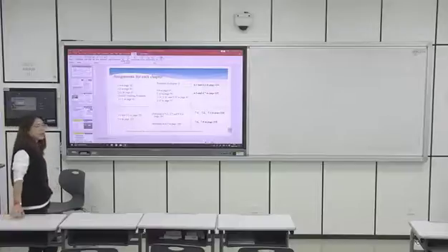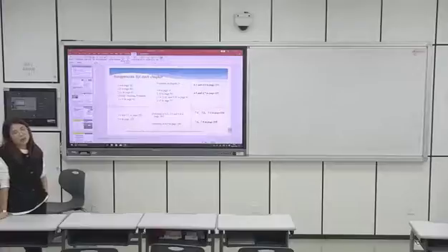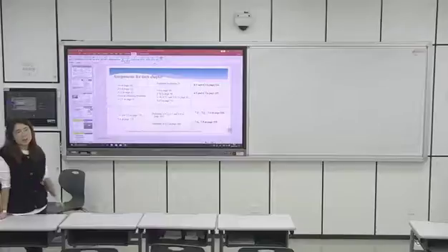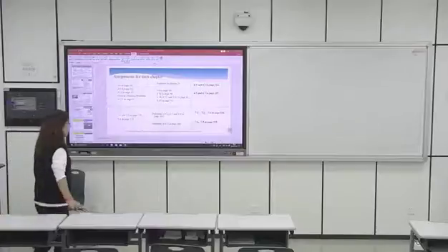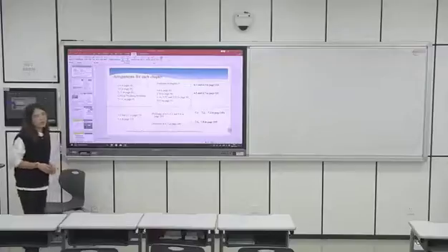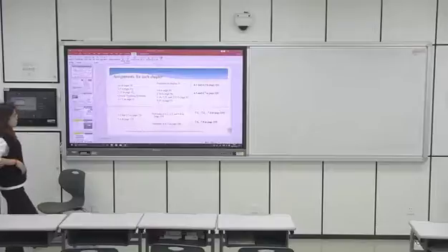And density. Density, we say that we have normal density or natural density. That is the weight divided by the volume of the soil. And also we have dry density. Dry density is actually the density where we exclude water. Only account the weight of the solids, right? So it is actually the weight of the solids divided by the volume of the soil.